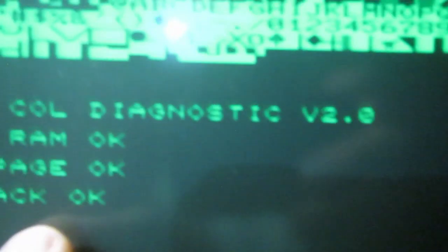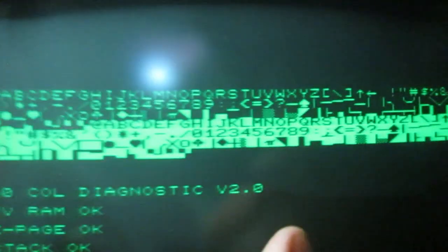So it seems there is a problem on data bus 0, which is not visible in this part of the RAM because probably this has been written before the problem started, and here the problem is evident because data bit 0 is always 0.